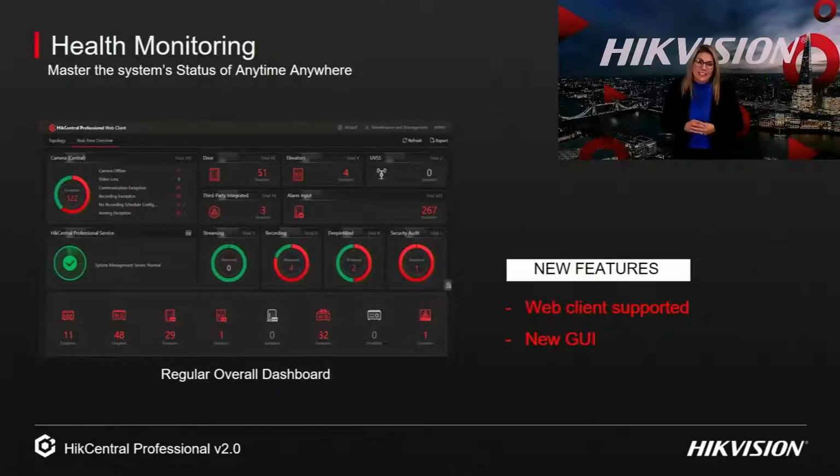Health monitoring as standard on the system and an essential part to the VMS. So this is where we can monitor every device on the system, whether it's access control, CCTV, or even third-party devices coming through. You can see on the image on the left-hand side, we have lots of different circles, some surrounded by green and red. Ideally, you want them all to be surrounded in green. Green means all good. Red means you potentially have a fault on the system.